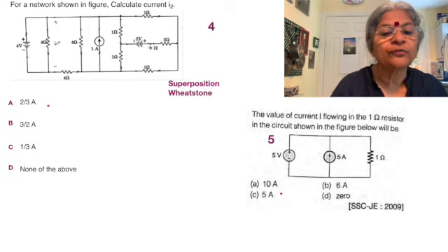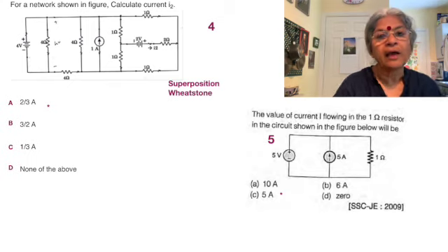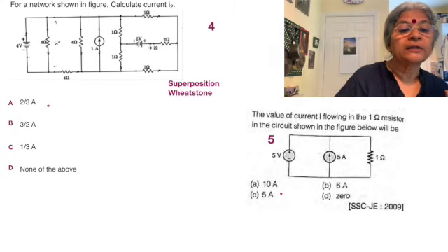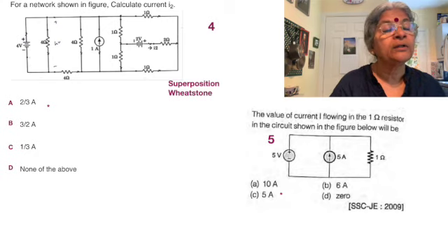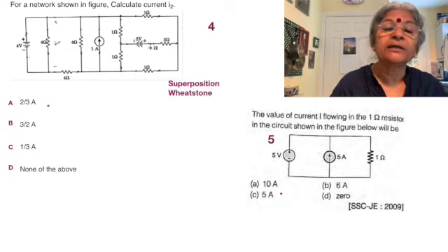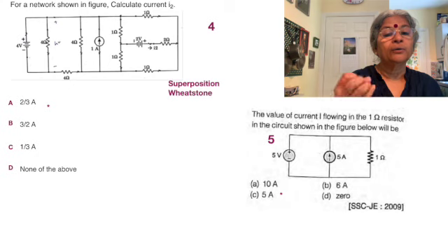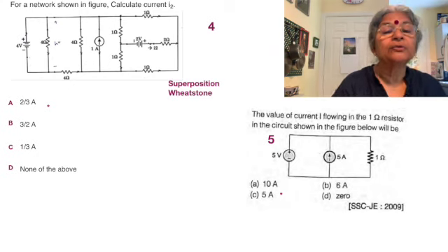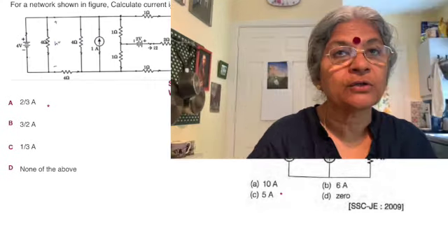But on either side of this central situation, we are seeing that there is a network of 1 ohm and 1 ohm. So on either side, we are actually having a Wheatstone structure if looked at from the 1 amp source on the other side, as also if looked at from the 4 volt, 4 volt in parallel with 4 ohm side. So both these sources now give rise to no current through the center of the Wheatstone structure. I suppose this is clear.